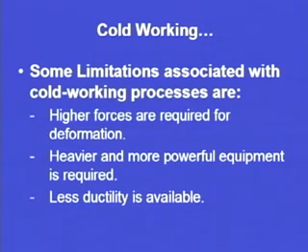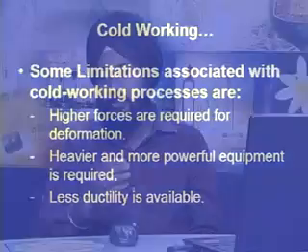So, that may at some later stage, under some loading, because this is not a single operation, it is a cyclic type of loading that is coming always. We are pressing or we are using the hammer or the punch to change the shape. So, under this kind of cyclic loading, sometimes if the bed is not sturdy, it may break. So, higher forces are there.